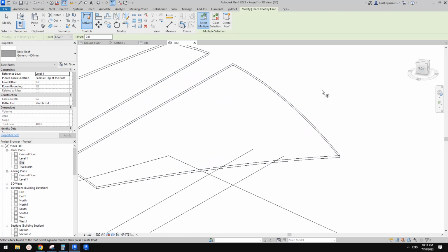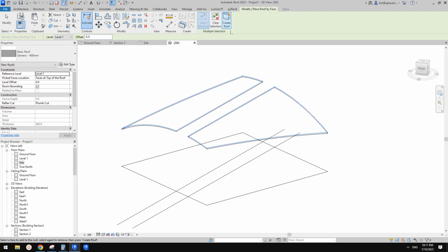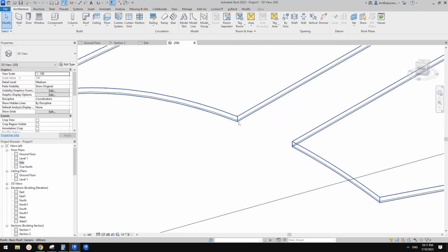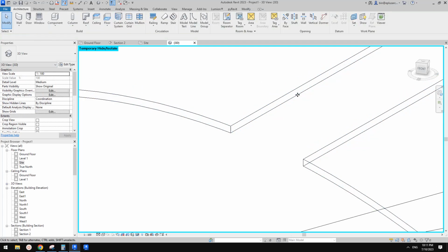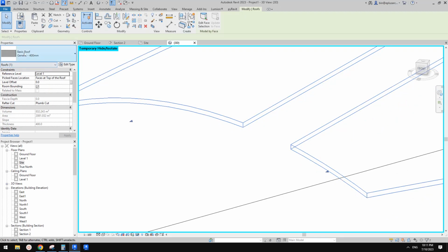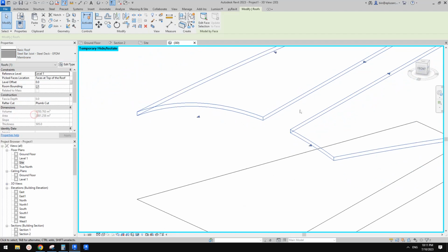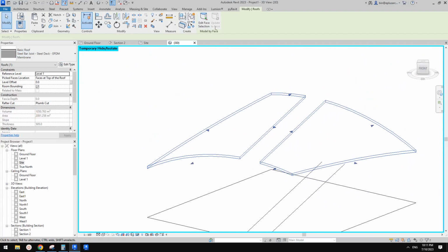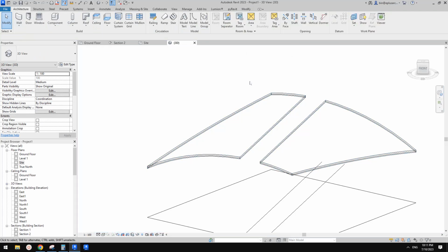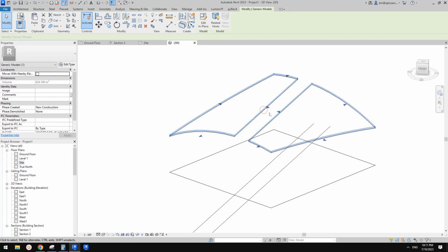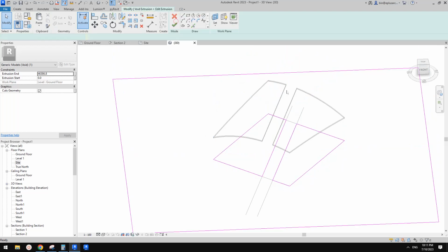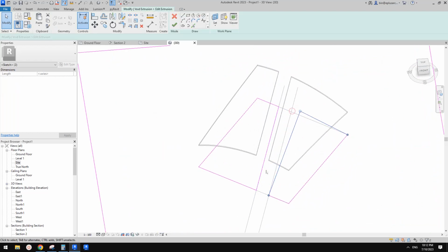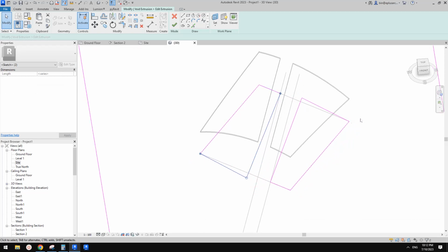Okay, so let's place it here, create a roof. So now you will see, other than this generic model, let me just hide it, we also have this basic roof, so we can change to any of these roofs. And also you can see here 'update to face', which means if you change the generic model, for example, I'll go to this generic model, maybe I'll just change the void. So maybe I'll change this, okay, a little bit.